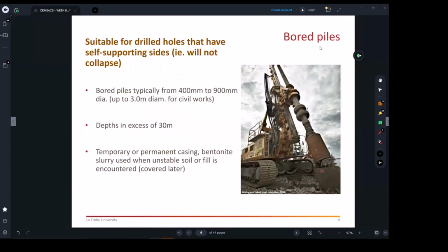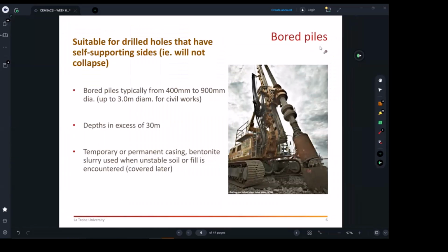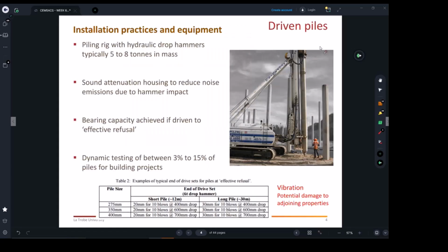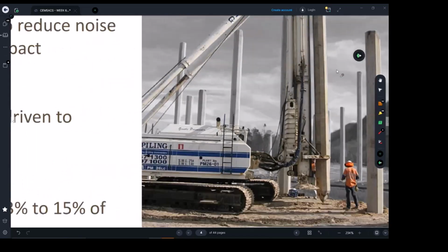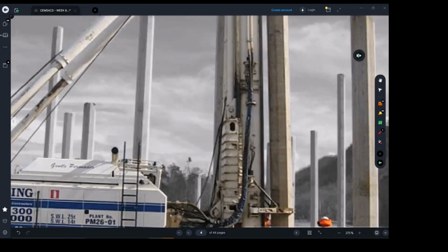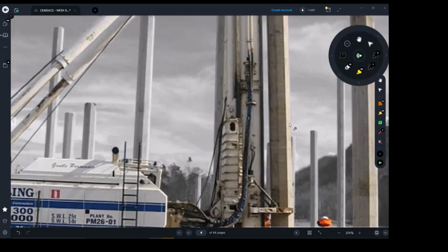So like you said, these are precast piles. You also said that you stop hammering after a certain depth or at an effective refusal. Basically, you stop hammering. So my question is, if you stop midway, what happens to the pile that remains above the ground level? Maybe, yes, excellent. You just saw cut it and use it somewhere else.